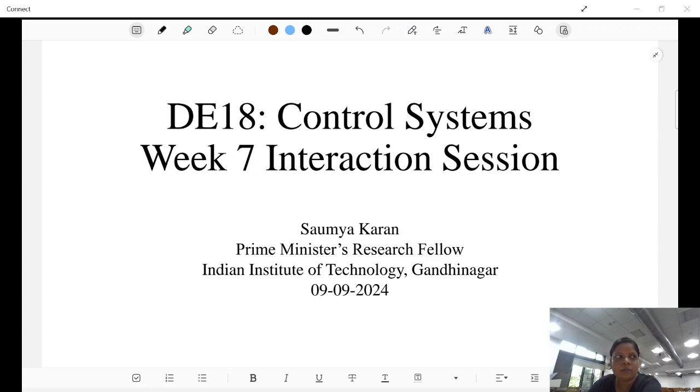So today also we'll have more questions on root locus, and it would be a more in-depth approach to find what behavior we get for closed loop poles, provided that we are given the open loop transfer function and we go on varying the gains of the system. Last time there was a question where we had a unity negative feedback system, and k greater than 0, which was the ideal case. This time we would have different cases also. You might have seen in the lecture that there are cases when k is less than 0, or it is a positive unity feedback system. So essentially the transfer function changes and the nature of the root locus also changes.